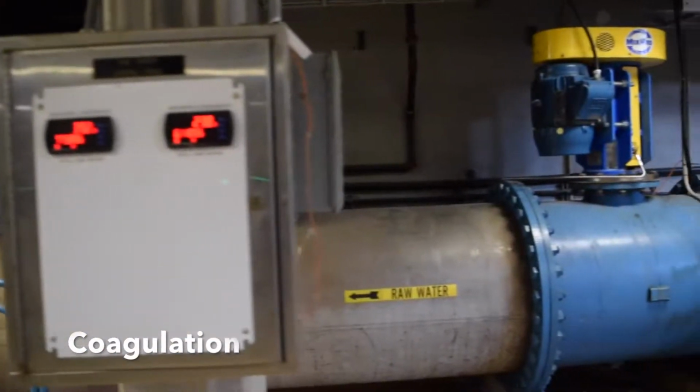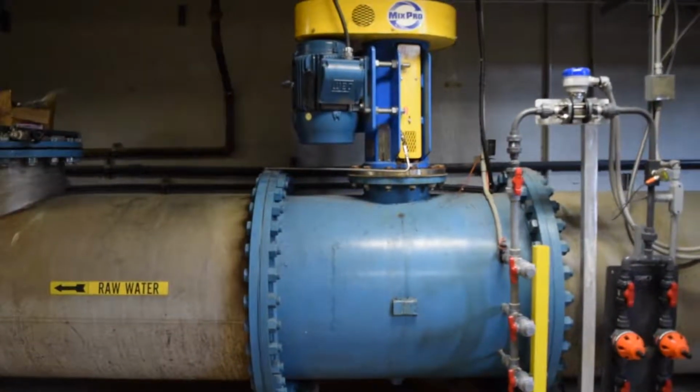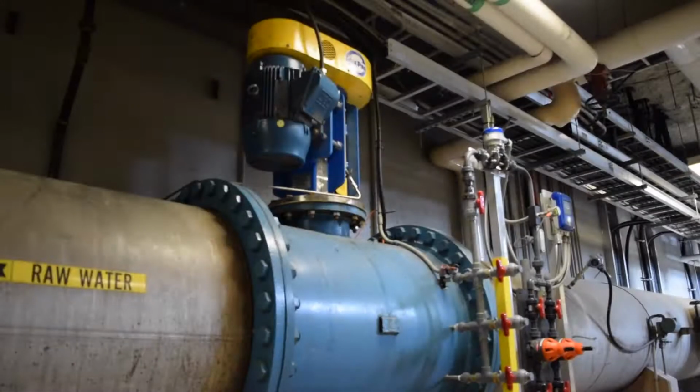Just slightly before the water makes its way to the flocculation tanks, it has to be injected with aluminum sulfate and quickly flash mixed with a large blade in a process known as coagulation. This process allows the particles to adhere and form larger and heavier settable particles called floc.